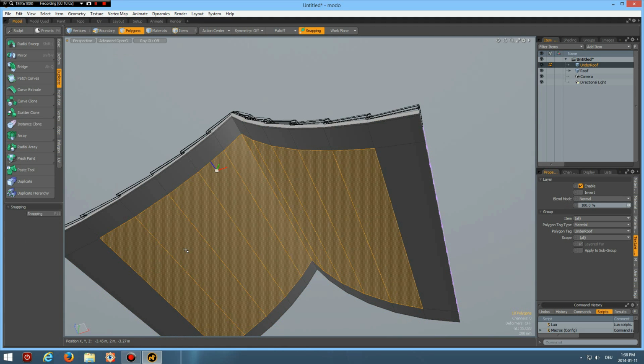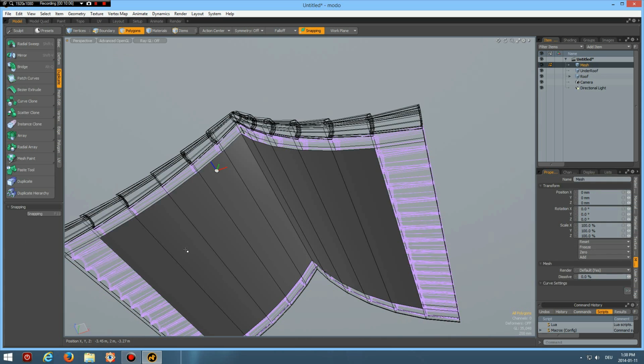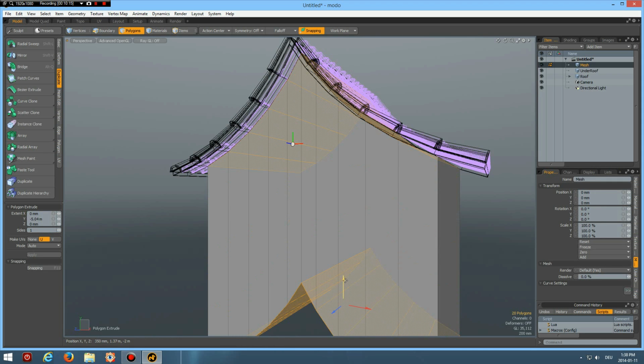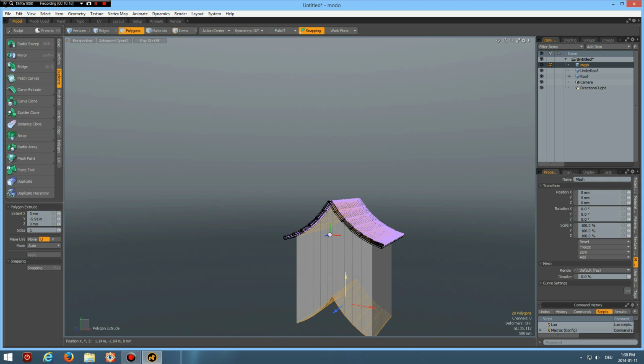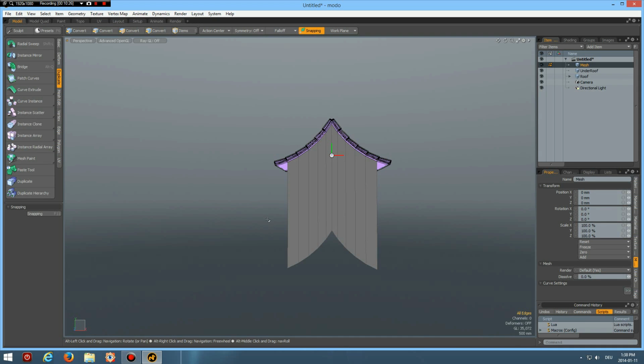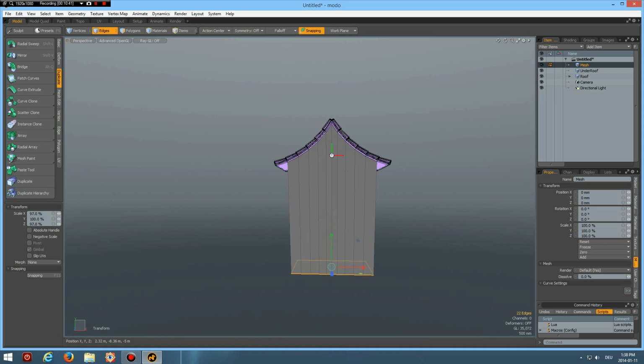So perspective. Now we can use this part here and make our house. Control copy, N for a new mesh, Control V, then Shift X again and bring this down to here. Yeah, and delete. Now in edge mode I select the bottom edges here, R key, and make them flat and maybe bring them down a bit more. Then R key again on the green circle and make this smaller.